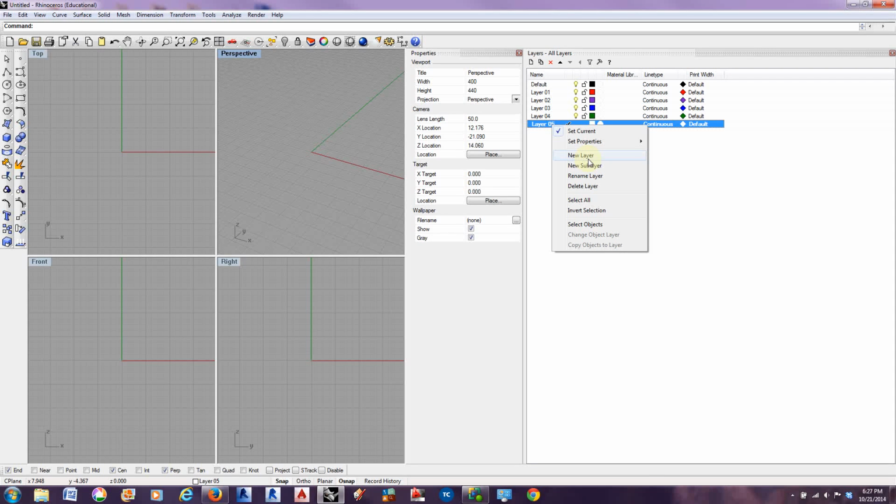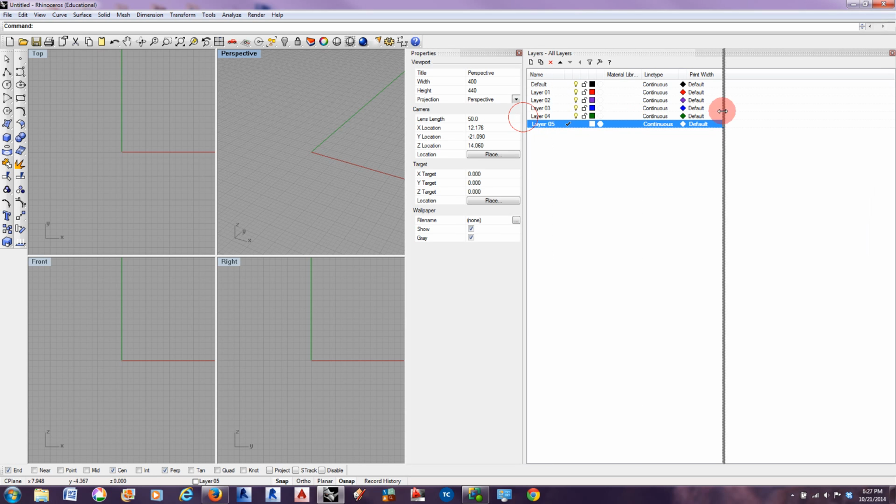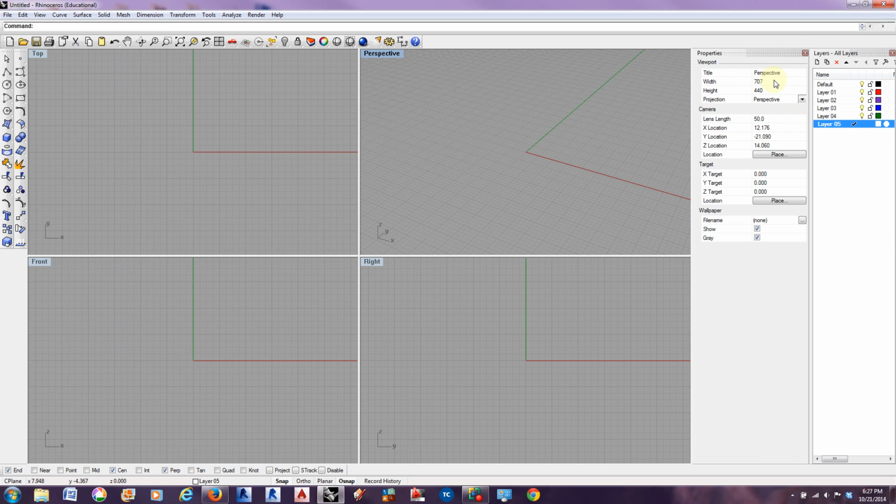Then you might think, okay, I need to put them on two separate layers, and now I need to create an additional material and maybe rotate the texture so that it aligns with the component a little better. So layers are pretty important to understand, and how you can manipulate them and use them to your advantage. So the layer tab is important, and it sits up here.